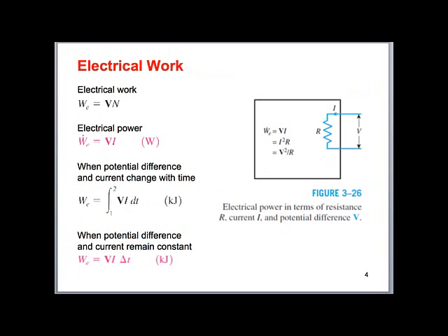One type of work is electrical work. If we have a resistive heating element in our system, we can calculate how much work is done in that system by multiplying voltage times current. The units of voltage times current are watts. If we multiply it by the change in time for how long we had that in our system, we will have the amount of energy transferred to that system. Depending on how you want to express that, you can show it in a couple different ways.